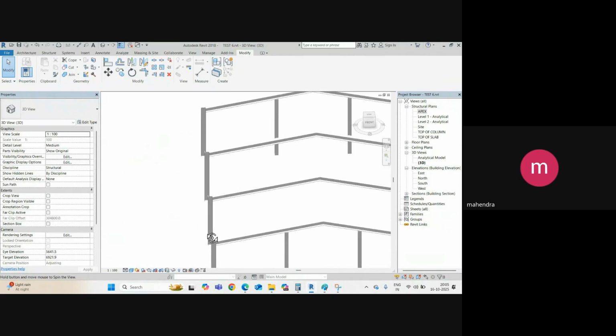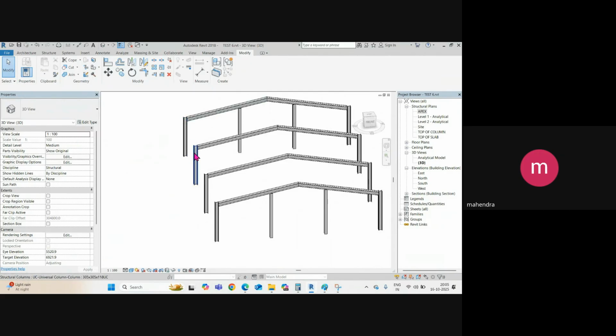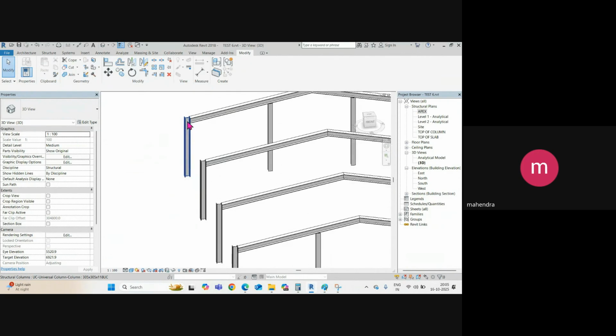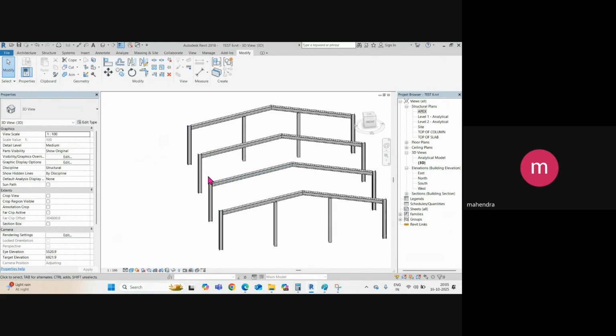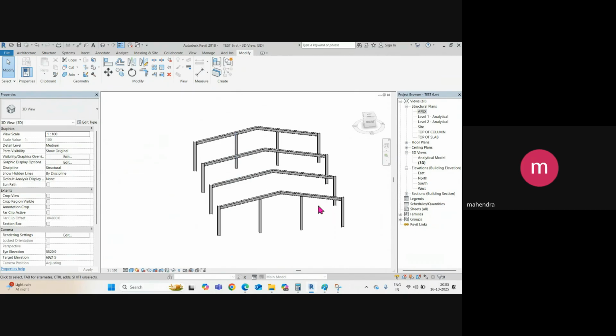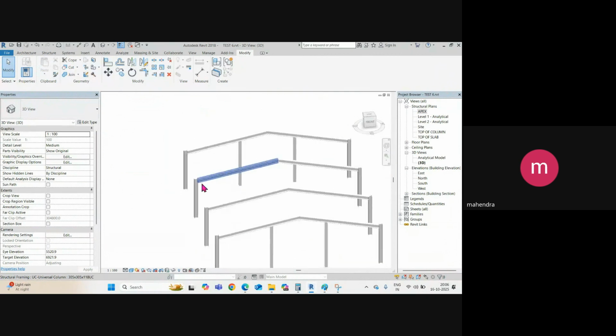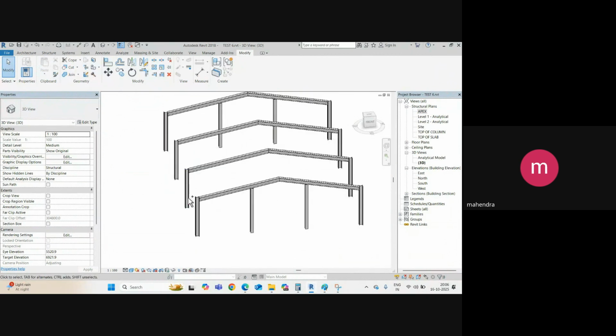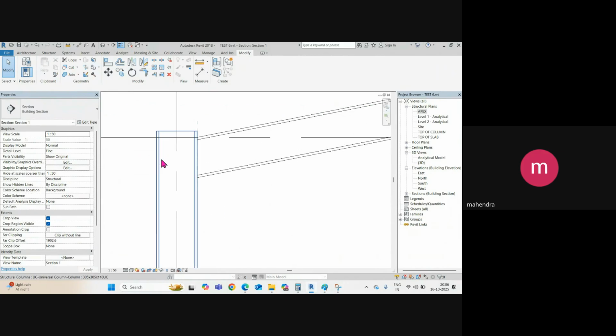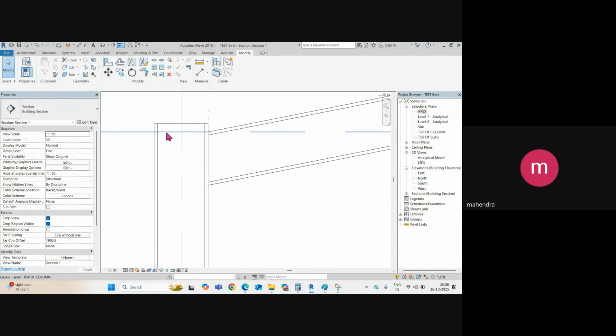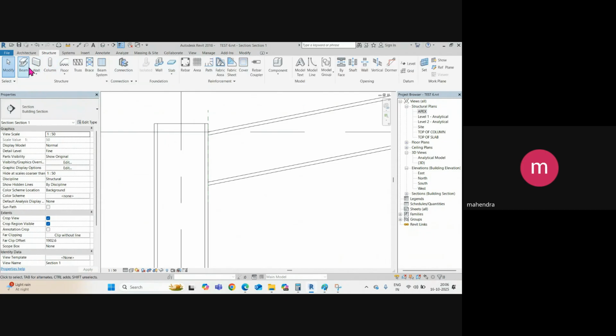Then you need to add the strut beam, connecting to all the framing here, all you can say girders. Suppose I want to add here. I have designed the, sorry, not I section, SHS. So I want to add the SHS here. I have designed, let's say, 100 by 100 by 6 SHS between the two frames. So go again to structural and say beam.